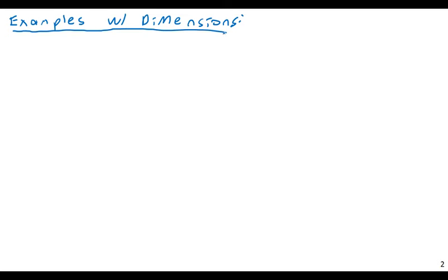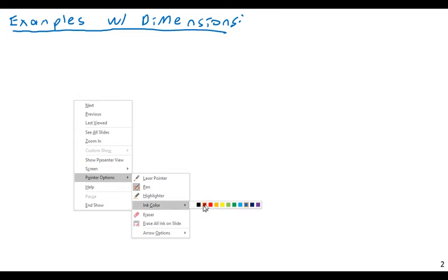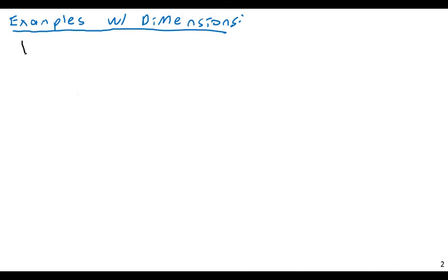Okay. Anyway, let's work with some examples with dimensions. Let me look at a few more examples. Let's say I want to verify the Reynolds number. That's something we'll see. The Reynolds number is the most common, what we call a dimensionless term. The Reynolds number is defined as density times velocity times diameter d, over viscosity mu. I want to verify that the Reynolds number is dimensionless.